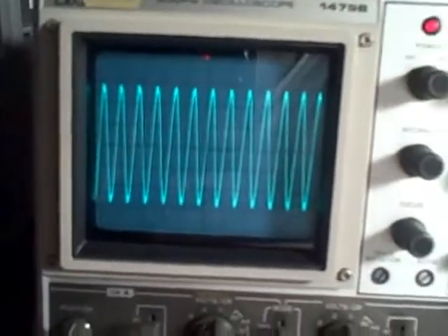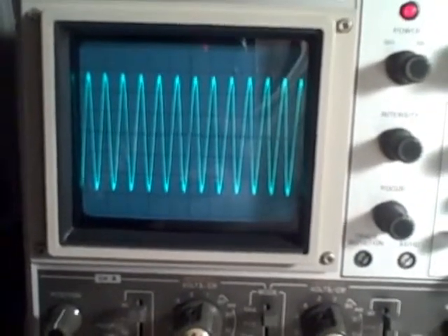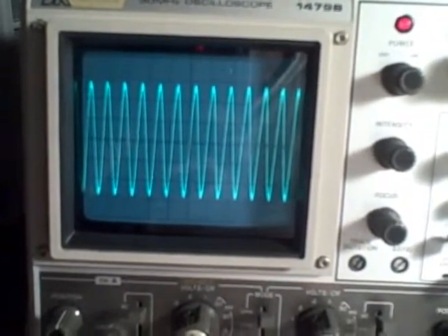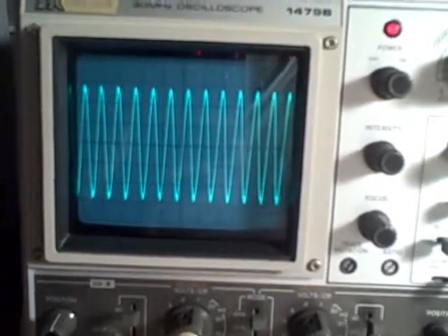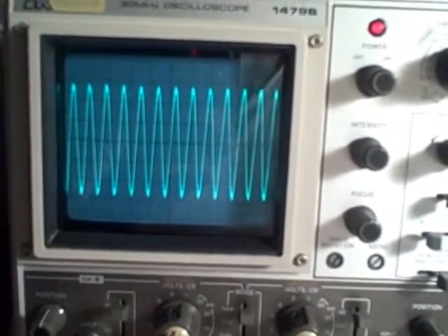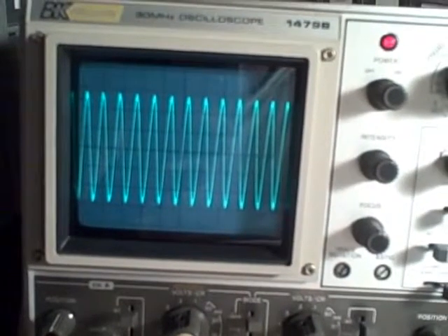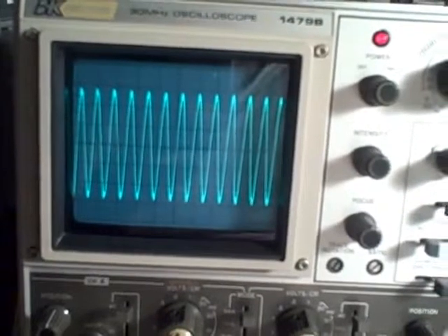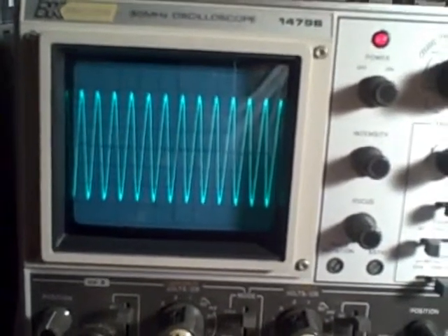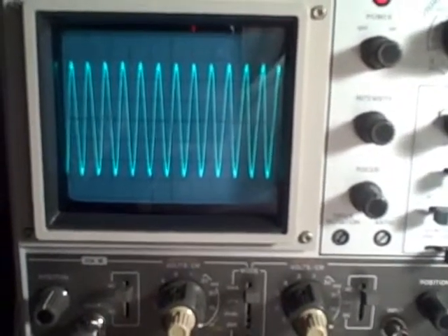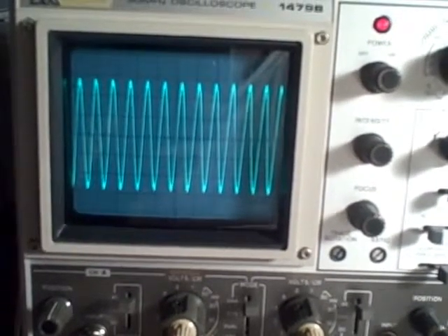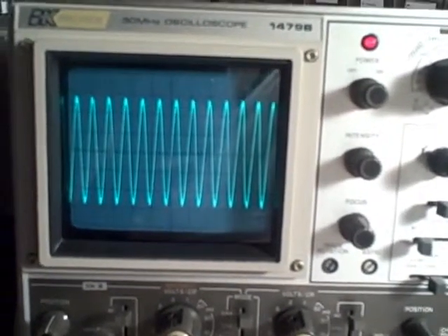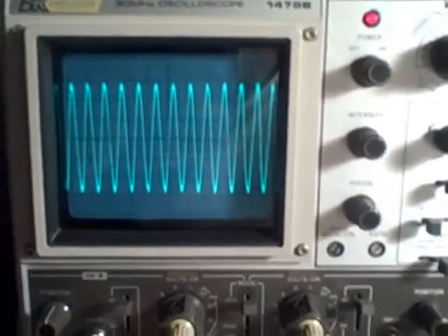All right, so 20 times the log to the base 10 of 2.8 divisions over the 4 expected is equivalent to a negative 3 dB. And so if we hit 2.8, we've gone down 3 dB on this scope. And on channel 1, channel A, it certainly appears that that's exactly where we are, at 2.8.